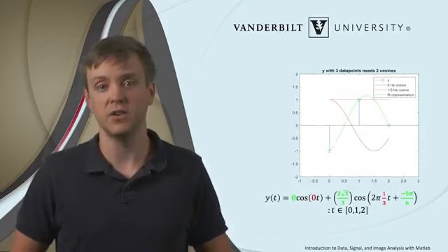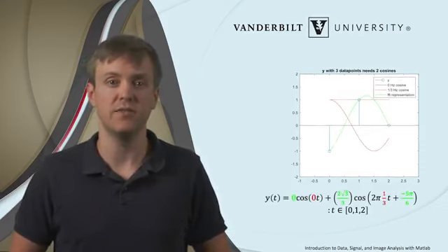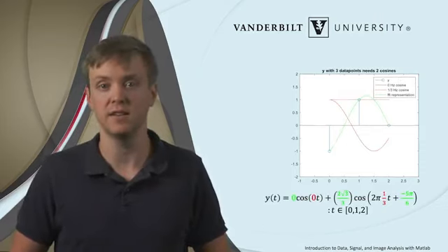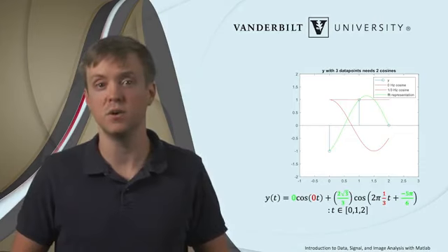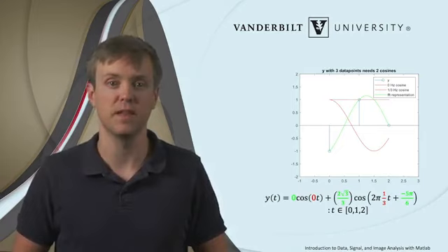The average value of our signal is still 0, so the IFFT tells us that in this case, again, we do not need any of the 0 hertz cosine in the IFFT cosine representation. However, for the 1/3 hertz cosine, we need a magnitude of 2 times square root of 3 over 3, and we need a phase shift of -pi/6.